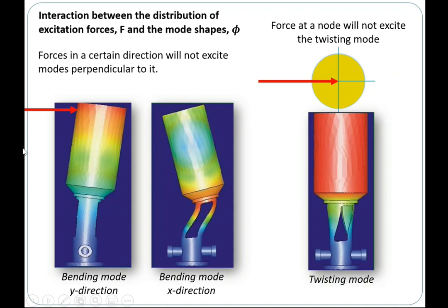If you have horizontal and vertical modes, and our beams are all vertical, and your force is acting vertically, you only have vibration contributions in the vertical direction. You will rarely have horizontal vibration in this case. So the modes that are perpendicular to your force won't be excited.